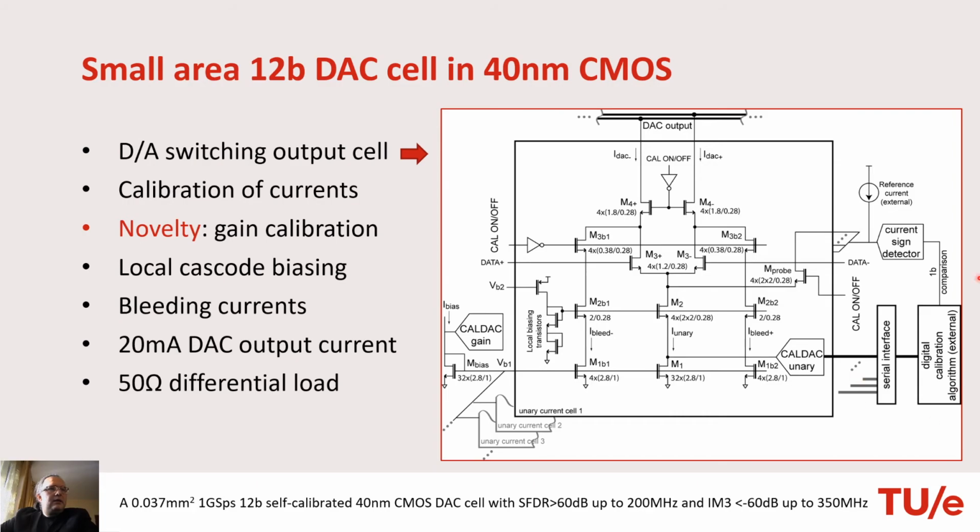And then this is read by the algorithm, and the calibration DAC word is updated according to the algorithm that I just discussed in the previous slide. And this is the output cascode. You see that all these transistors are thick oxide transistors. This is the requirement for the integration of the DAC unit inside the I/O bank.